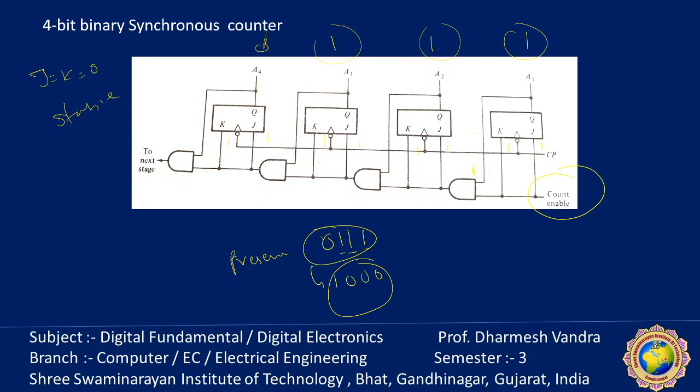In the synchronous counter, the flip-flops trigger on the negative edge, and this is essential here, whereas with the ripple counter the counter could be triggered on the positive edge of pulses. Here it is 1 to 0. Remember that only the 1 to 0 transition is possible, so this circuit is only for the negative edge.